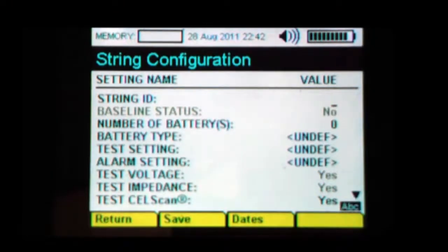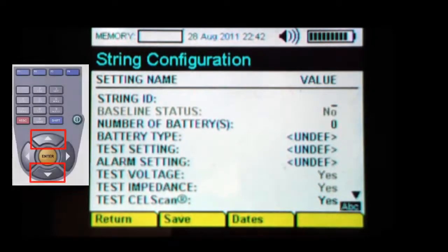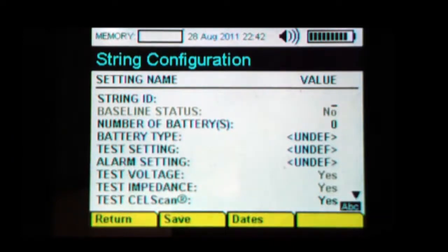The string configuration screen is displayed. Navigate with the up and down buttons between the different fields, and use the right and left buttons to scroll between testing options. Use the keypad to enter information. Note that you can increase or decrease numbers by using the left and right keys. If parameters are missing from some inputs, the analyzer will display an error message indicating the missing components. Ideally, create a string configuration using the natural filling order of the screen.